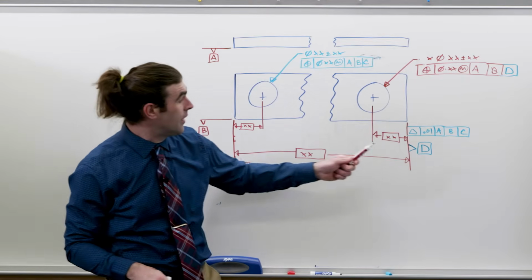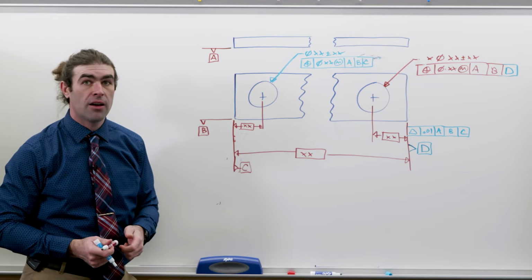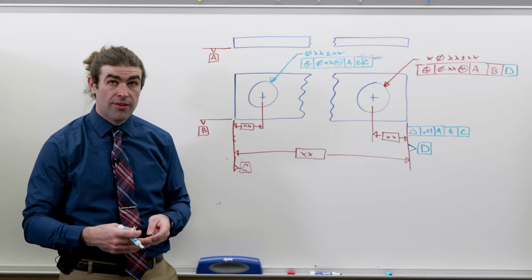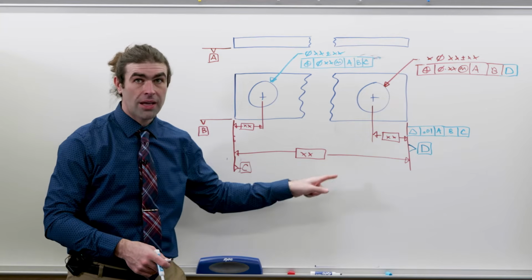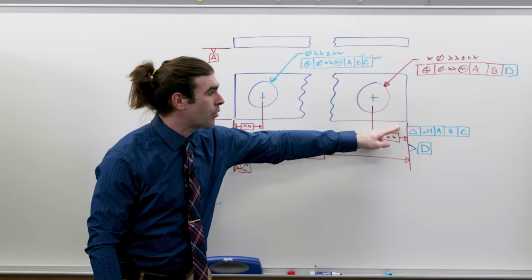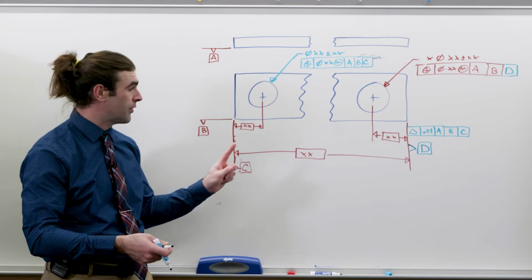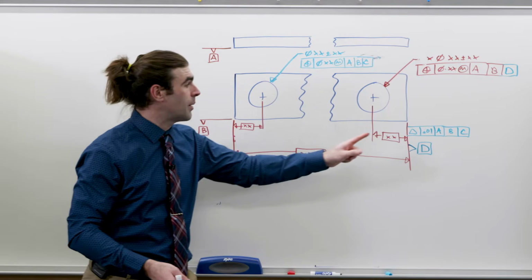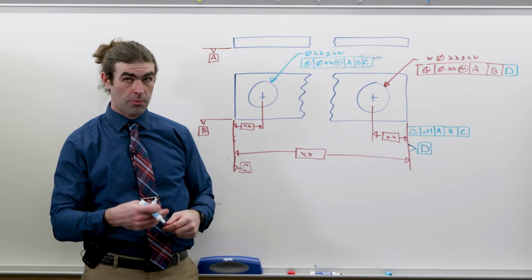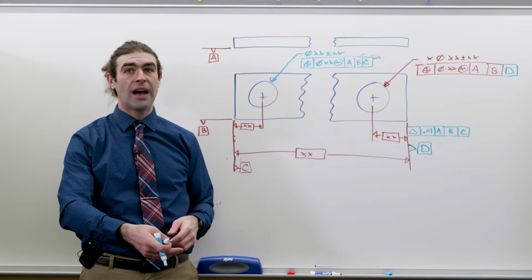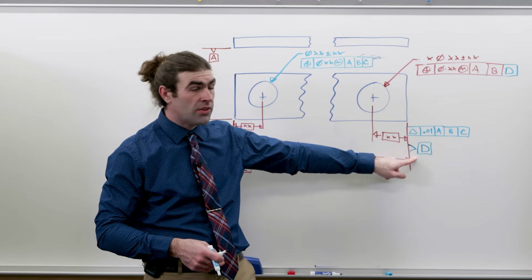So we're going to add datum D, which we're going to establish as this side of the part. We need to have a tolerance for that datum because we're using basic dimensions. We need a profile to establish the location of that surface from this side. So that profile is going to be to A, B, and C. So we're still going to have to measure that to make sure that's within tolerance, that comes and makes datum D.